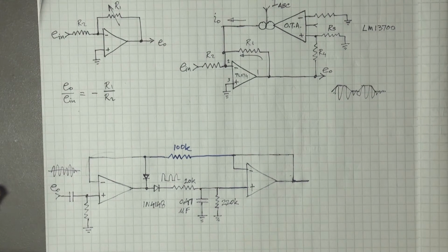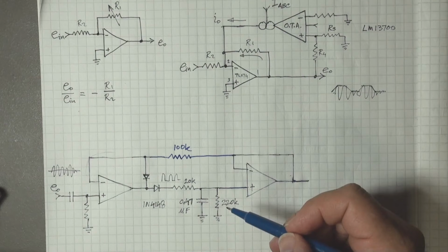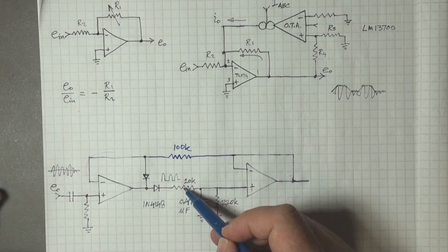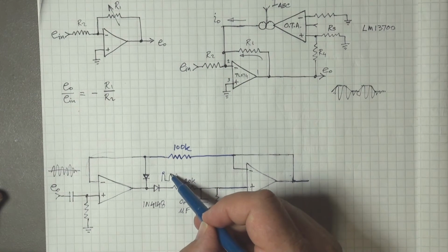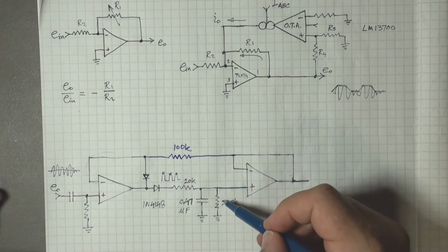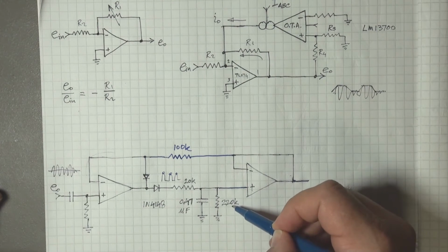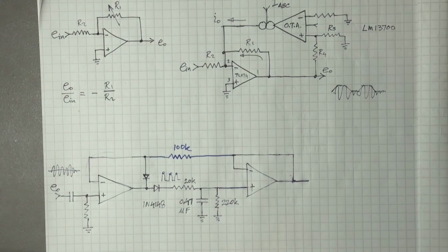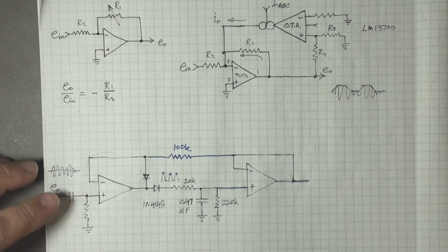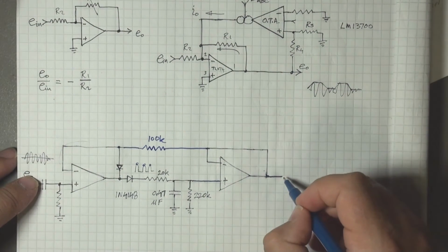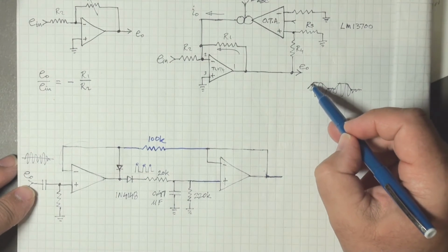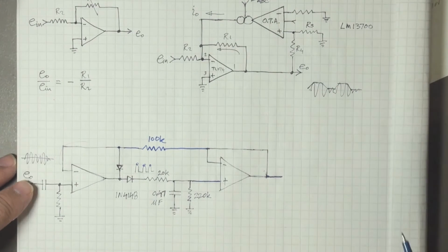So the action of the circuit is such that this capacitor charges up very fast through this 20K resistor on the positive peaks of the voltage swings, and it discharges slowly through the larger one, 220K. In other words, it holds the peak for a little while. And so what do we do with the output here, which represents the envelope level of the output?